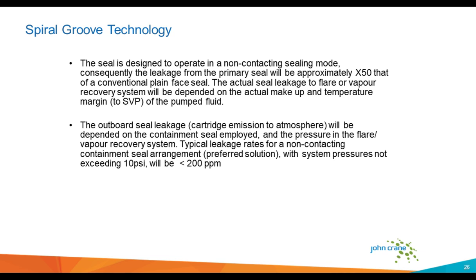The outboard seal leakage is normally non-contacting. This is preferred, and that seal normally runs on either nitrogen or what have you, with a process pressure not exceeding about 10 psi. The leakage to the atmosphere with that containment seal is less than 200 parts per million.